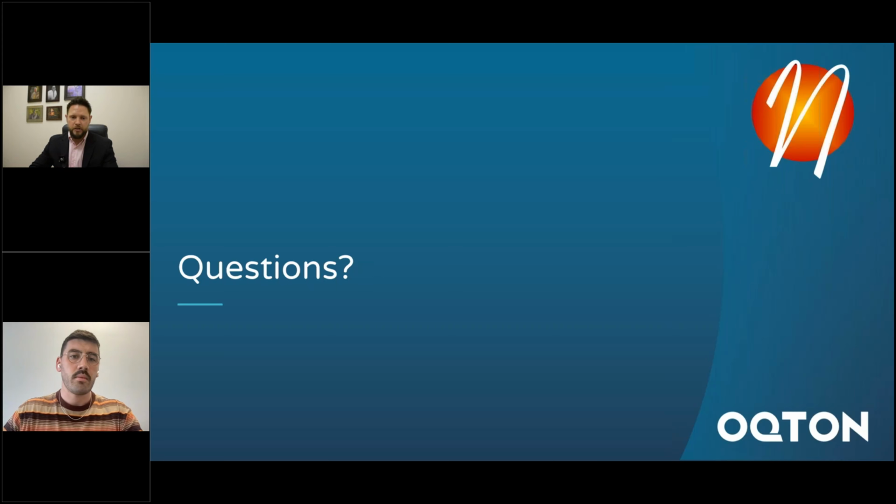Yeah, great question. So you don't need a CAD file. It's always a little more streamlined to set up when you have a CAD file, but you can certainly bring in a scan and use that as the reference or extract reference features from it. And then obviously you can measure the part to itself. From subsequent parts, you can import a new scan with that old one as the reference.